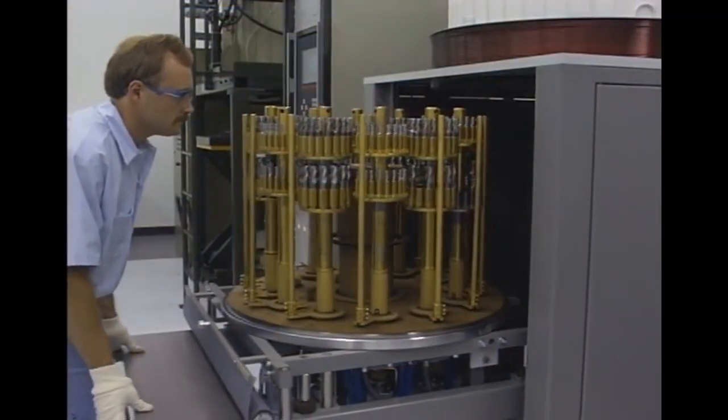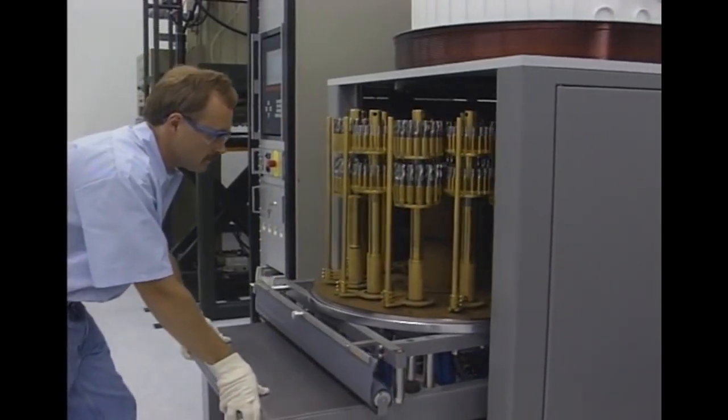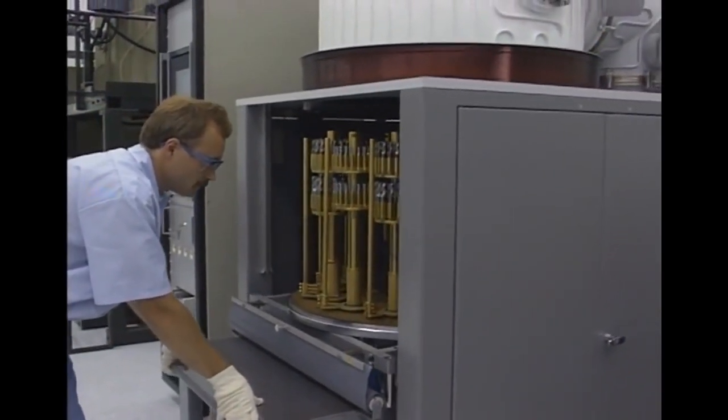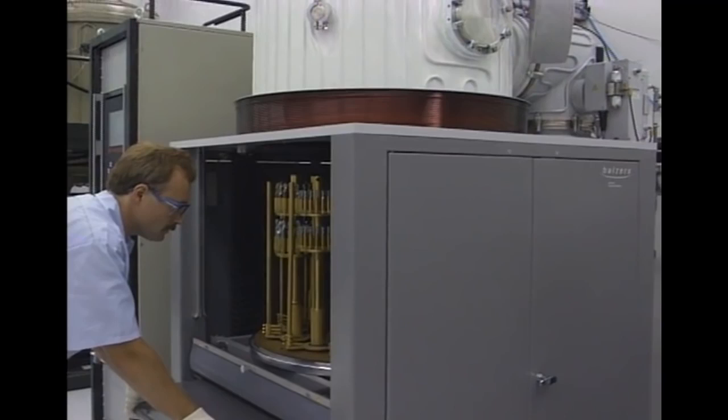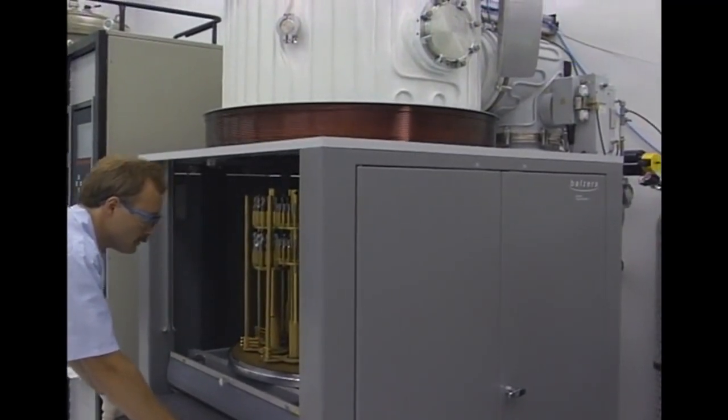The physical vapor deposition method takes place at temperatures around 500 degrees centigrade and is used for single-layer or dual-layer coatings. Coated carbides are more costly on a per-insert basis than uncoated inserts, but they achieve greater productivity. In terms of parts per edge, the coated carbides have the advantage.